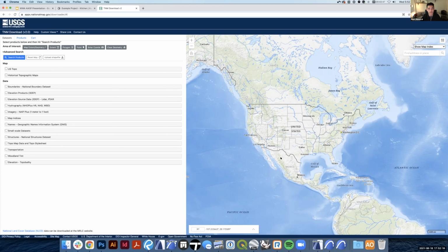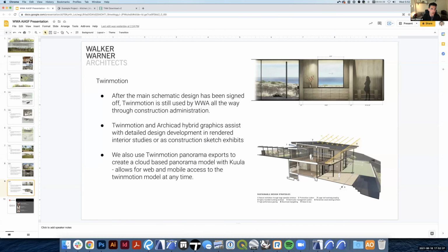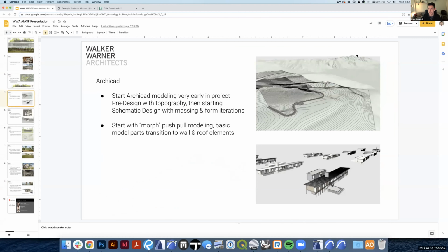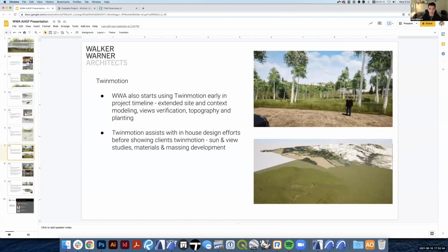then sometimes you're taking the height map data from the US government survey, transitioning that into contours, loading that into Rhino, baking a mesh using a Grasshopper script, and then taking that mesh and applying a Google Earth texture of the same area, perhaps in Rhino, and then you're able to load that giant mesh into Twinmotion, and also into Archicad. So you can generate low poly versions of that topography, or like I've shown here, get huge versions of the distant mountains.